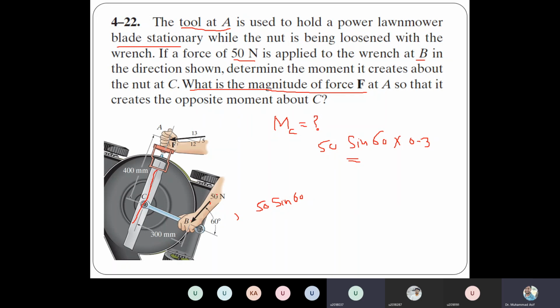I got your point. Basically this is 50 Newton. Now we can resolve the component. One component is the vertical component, and the other one is this component. We know that this component is in front of the angle. If we draw parallel to this component, and this angle is 60, then this is parallel to this one, so this is basically 50 sin 30.